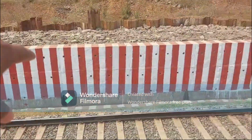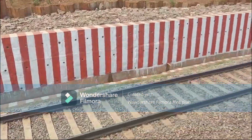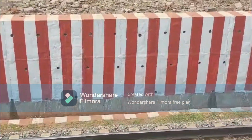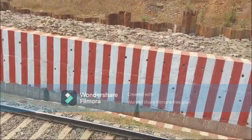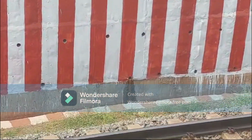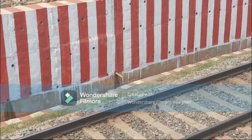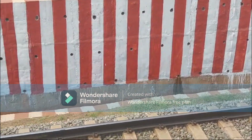And there you can see the weep holes in the wall, because rainwater can seep and permeate through the boulder layer. You can also see the groundwater level is so high that water is seeping through this borehole, weep hole, with some wetting and some seepage.